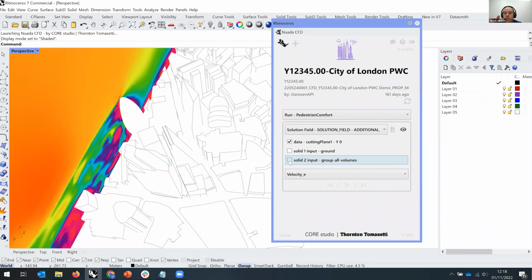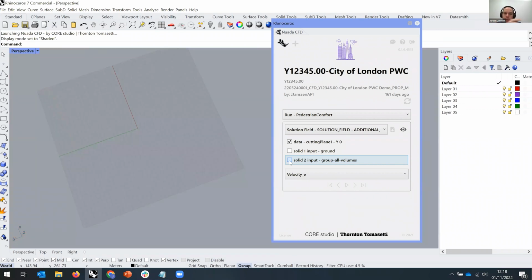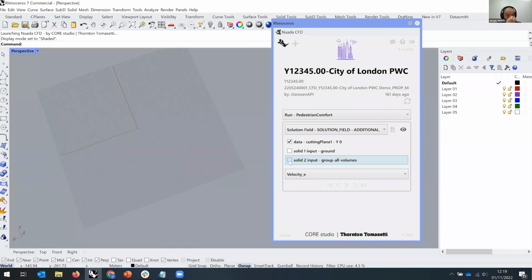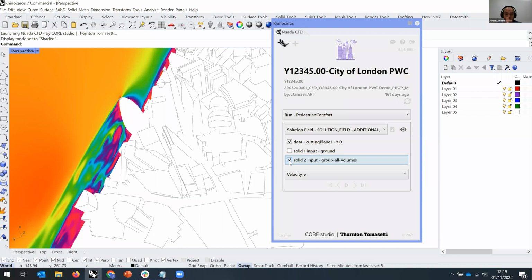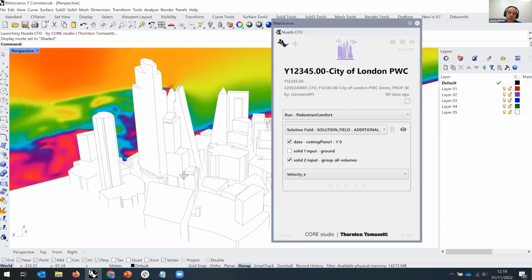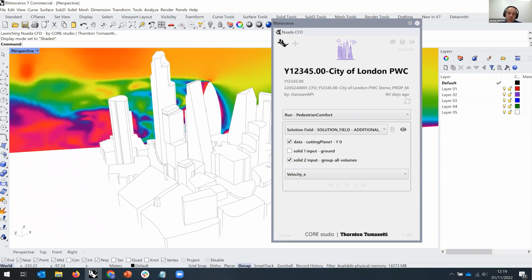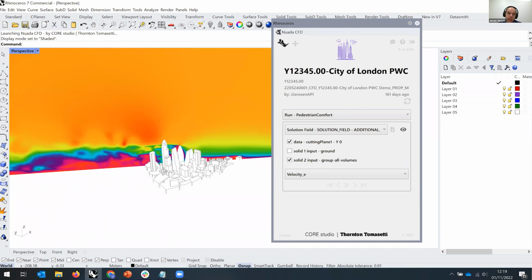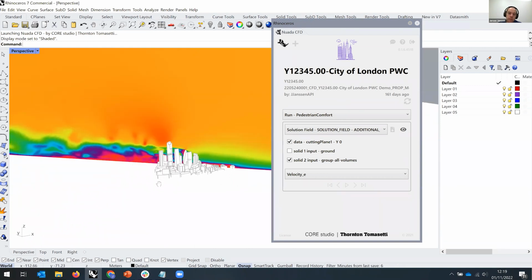We're also thinking about a few post-processing routines, mainly to combine it with structural analysis, to get the overturning moments or pressures on a facade into structural analysis to compare it with, like, a Eurocode wind analysis. We need to think about how we're exporting it, but that's in the works, basically. So that's pretty exciting.